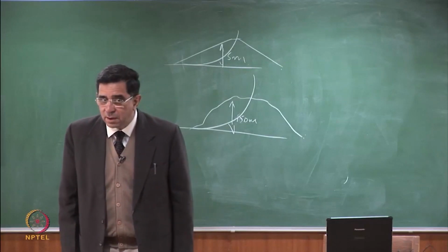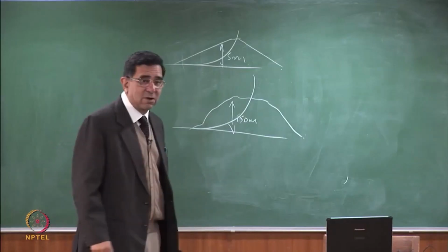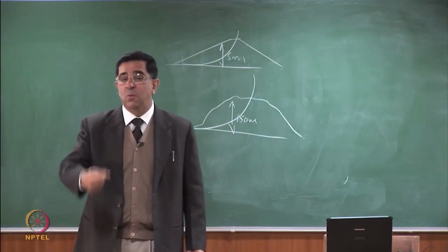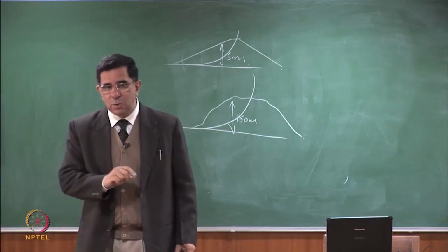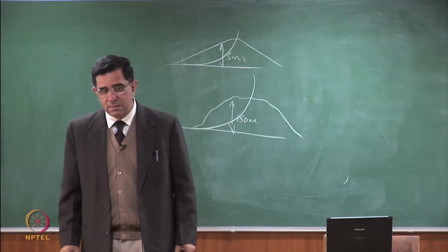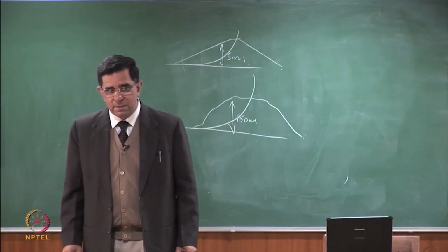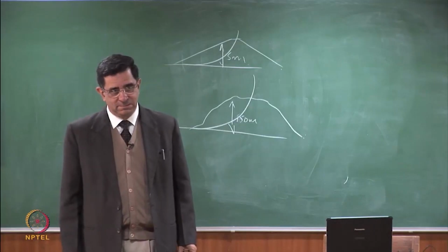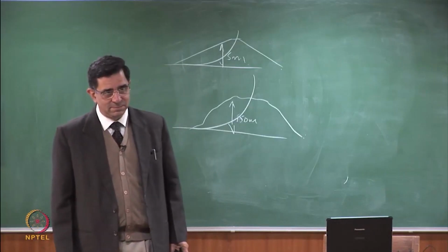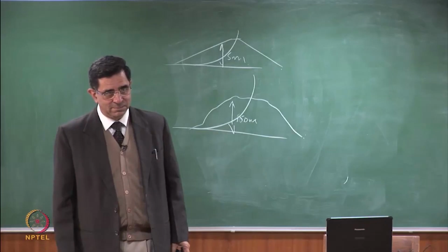What depth? There is no wedge here. This is a circular failure surface. You are saying if the wedge depth is to be considered. You are almost there, but there is no wedge in this analysis. If we consider it as finite, then there is already some weight which is supporting it. It cannot have a circular surface because then the slope below it would be supporting it.